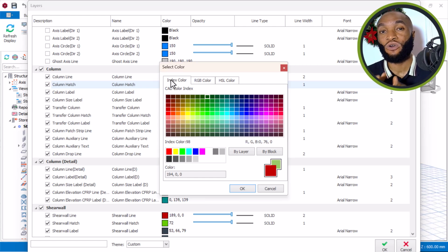So avoid using these three colors, red, orange, and yellow, for your 3D look, because people that know the software, merely seeing red colors on your members, will assume that member is failing, and that you don't know what you're doing, not knowing that it is just the color you chose to use. So avoid using member failing colors.